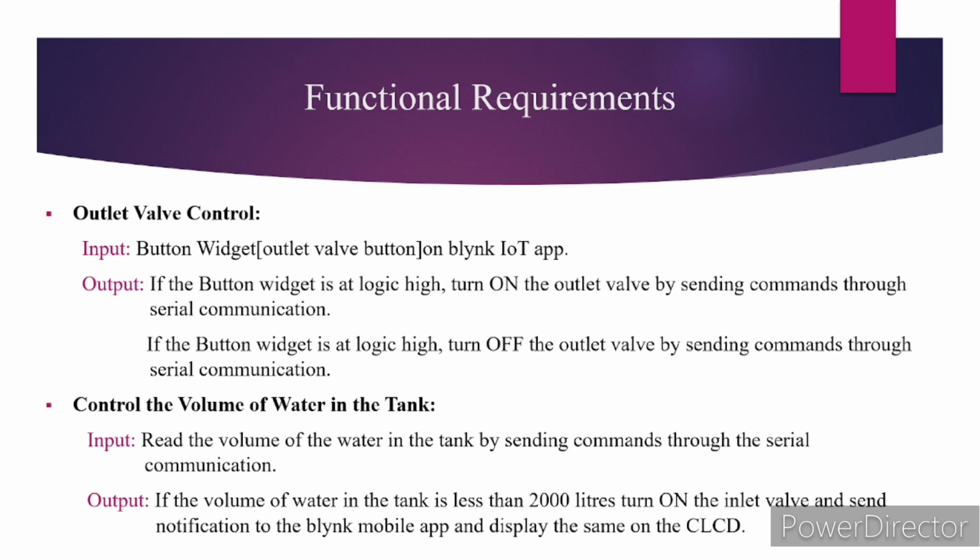And the last is to control the volume of water in the tank. In this, the input given is to read the volume of the water in the tank by sending commands to the serial communication, and the output is, if the water in the tank is less than 2000 liters, turn on the inlet valve and send notification to the Blink mobile app by displaying the same on the CLCD.